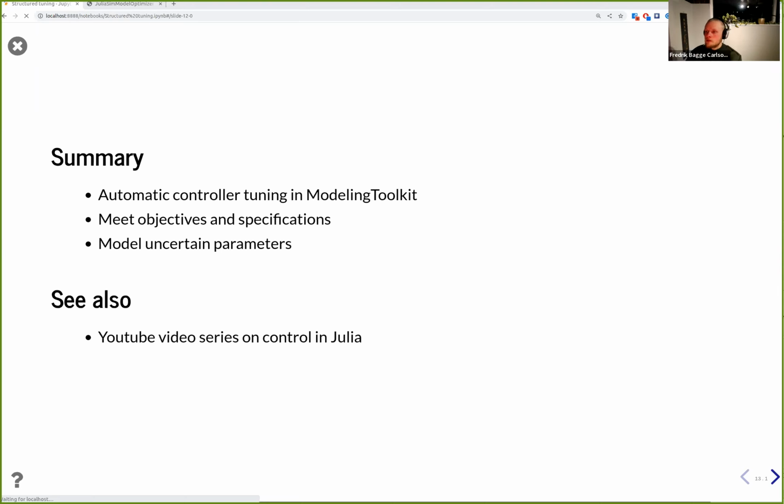So I'm not entirely sure what that means. ModelingToolkit is just a model compiler. So what ModelingToolkit does is it allows you to write your model. And then when you are done, it performs compilation of that model. So it performs model compilation steps like pairing and alias elimination and things like that. And then it will write a code, Julia code, that is the right-hand side of your DAE in general. So for simple systems, it will be an ODE, but for complicated systems, it might be a differential algebraic equation.